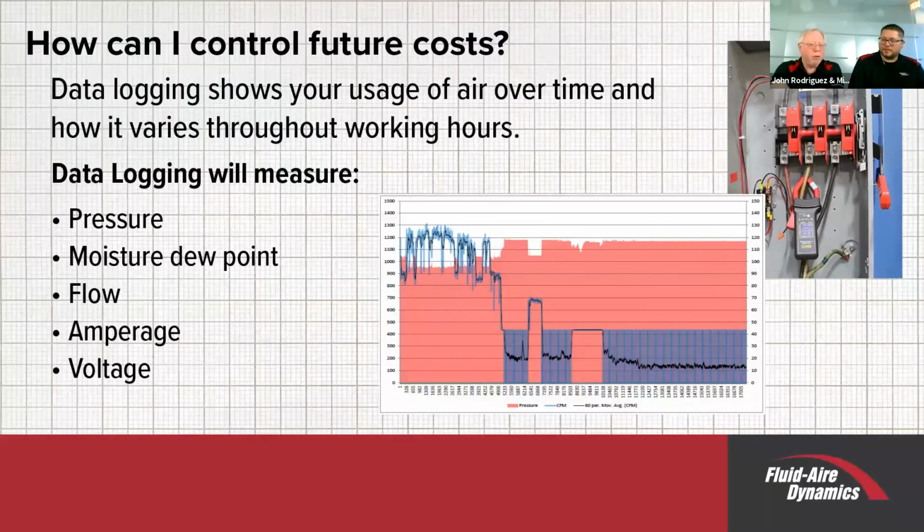We offer at Fluid-Aire, and so do other people, offer data logging. Data logging is important to have a baseline of what's going on in your facility, knowing how much air you're using today versus how much air you're using tomorrow. And why is the air increasing tomorrow versus today? Did we add equipment? We needed the air. Did we not add equipment? Do we have more leaks? Do we have our people out there using air inappropriately? On the other hand, having that baseline allows you to work from that point and see whether the usages out there are really doing work for you as opposed to just being wasted air.